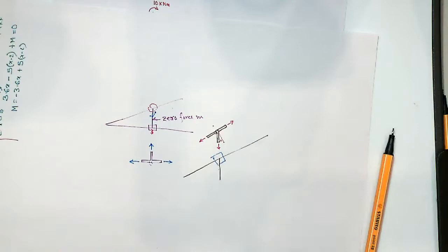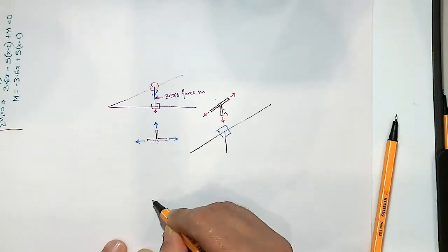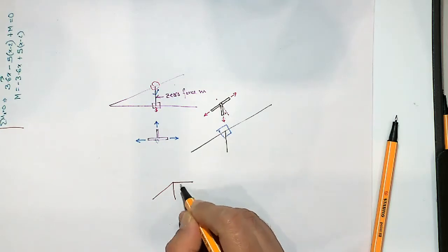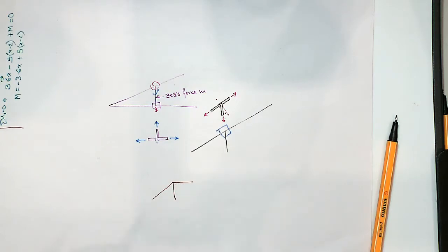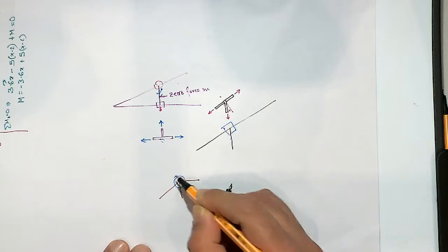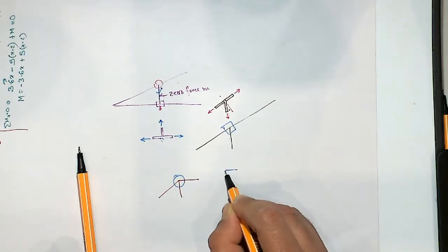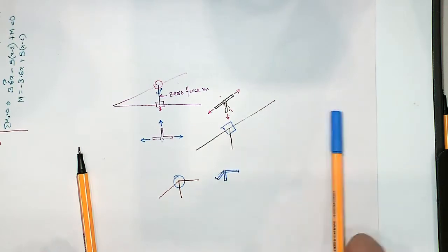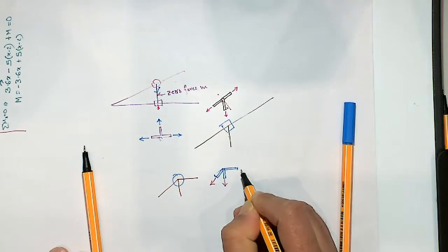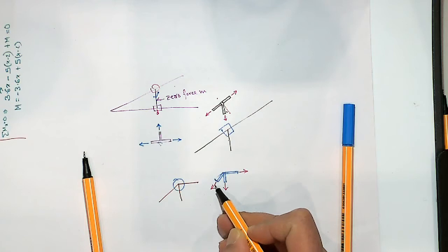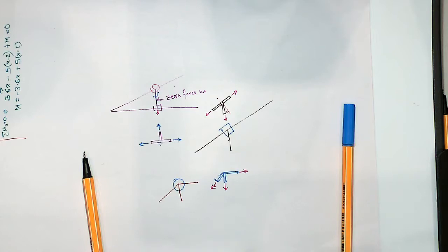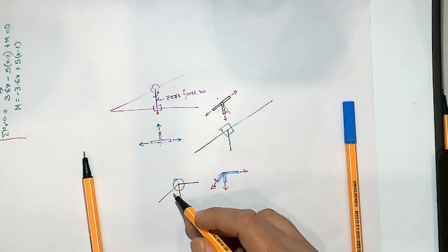that doesn't mean that, so this would be a zero force member. Now, if at a point you have got three members like this, for example, that doesn't mean each of these or any of these would be zero. Because if you take the joint here and draw them, so you have got one member goes that way, another member goes that way, another member goes that way, for example. So you have got three forces. So the horizontal component can be taken by the horizontal component of that. The vertical component of this can be taken by the vertical component of that. Okay. So if two of them are not along the same line, it's not very obvious whether something would be a zero force member.